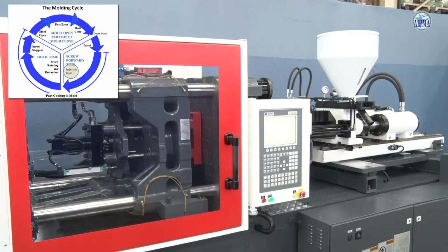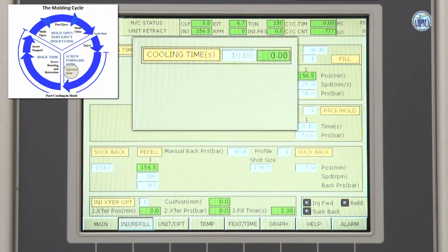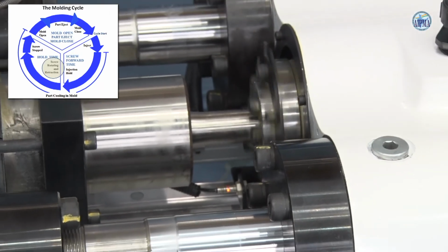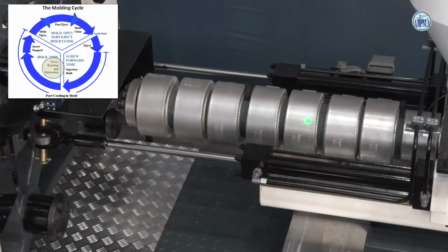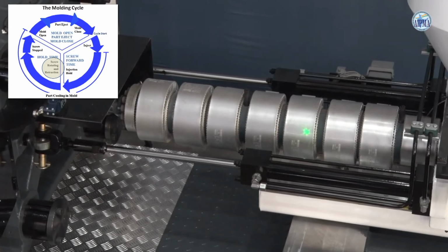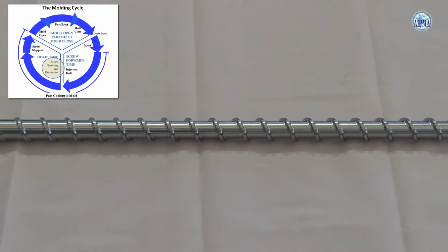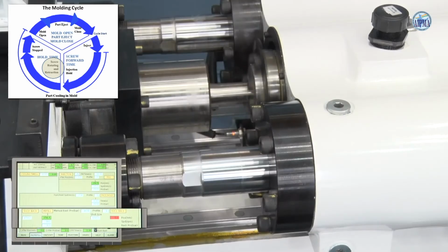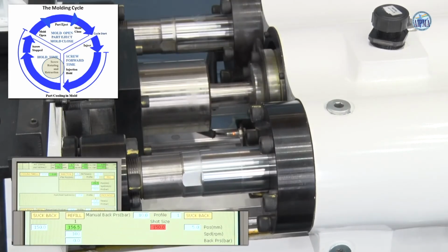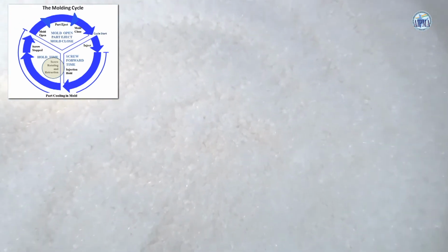Cooling. The injected material should be allowed to sufficiently cool before it is ejected. Refilling. During refilling, the screw is rotated by hydraulic motor and plastic granules driven forward through screw flights. Plastic granules are softened by external heat and melted by shearing in screw flights. For better plasticizing and homogeneity of plastic melt, back pressure is to be applied. The screw speed can be controlled depending upon the type of material used and temperatures set during refilling.